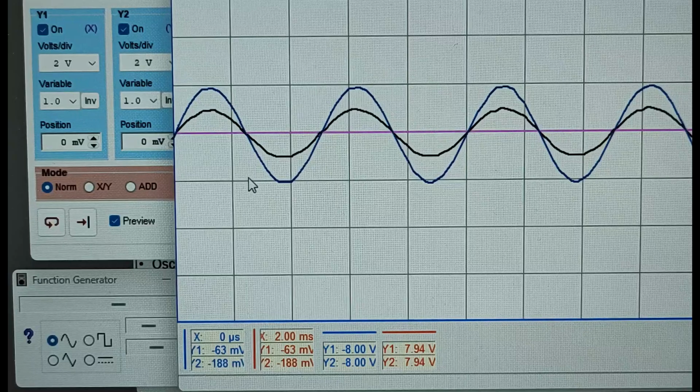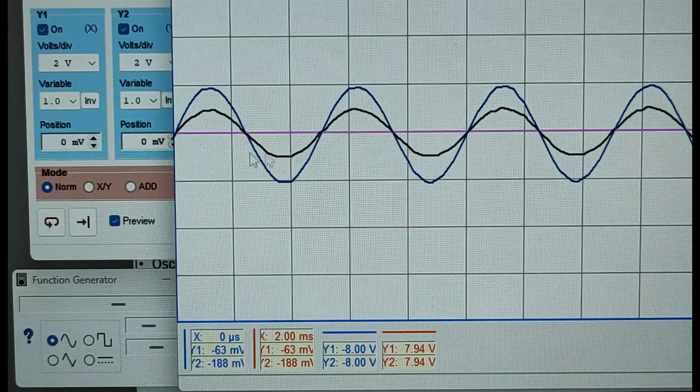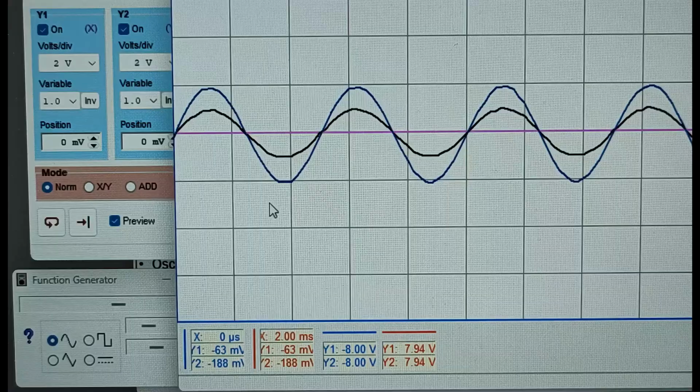Another thing, phase relationship. You could also see it here. How? Notice there's no actual separation on the waveforms, both input and output. Both of them are starting and ending at the same time. If you take one cycle, that's very clear here. So if there's no actual separation on the waveforms, the phase relationship for those two waveforms would be at 0 degrees.